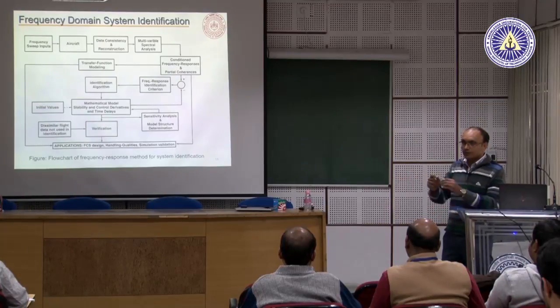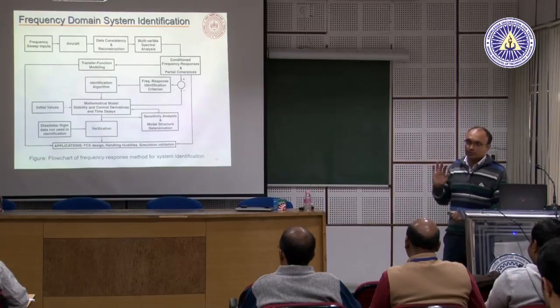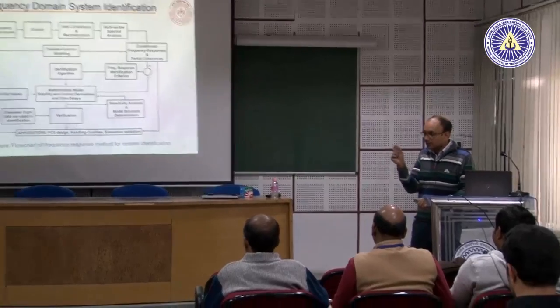Normally your helicopter is flying, and you give some input to maintain the position. Now the pilot will on purpose try to excite the motion in the helicopter. So he will give very fast inputs, changing the various input sticks, that is the cyclic stick and collective stick. Of course, for a small helicopter we don't have cyclic and collective physically. What we have is our remote control, which has a throttle and a side stick.